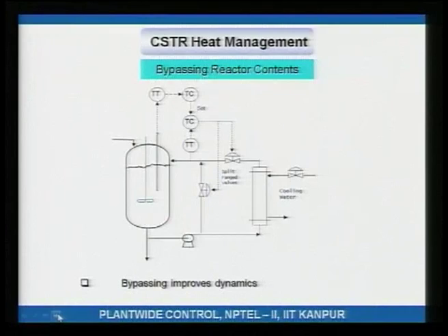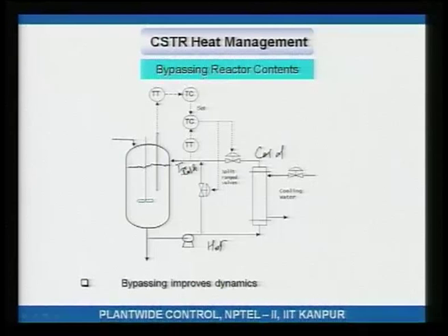Now a part of the hot material is split, the hot and the cold streams mix, and you get whatever is the cold temperature that you desire. The working is very similar to what we just saw a couple of slides ago. This is the bypassing of the heat exchanger, so let us say 10% goes out here, 90% goes down there.